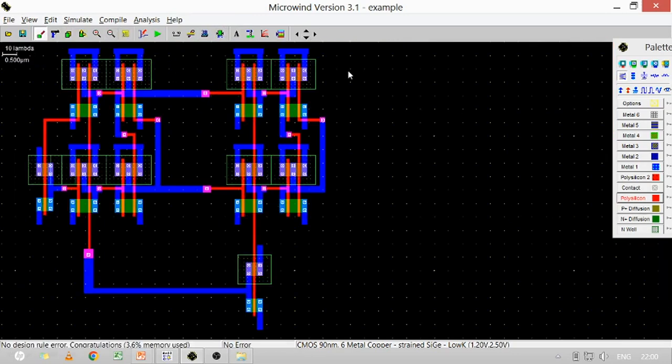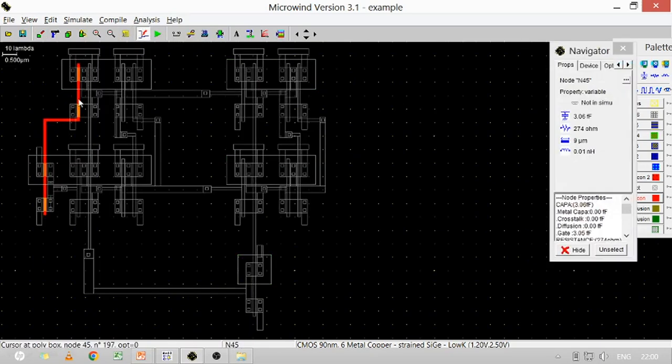You can once again cross check by electric node. So we are having the electric node. First we check this is input D. Then the output of the inverter becomes the input of N2. The clock is the inverted clock. So the same clock is given to that slave.